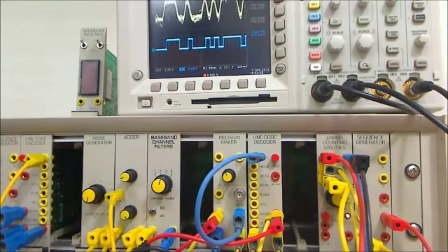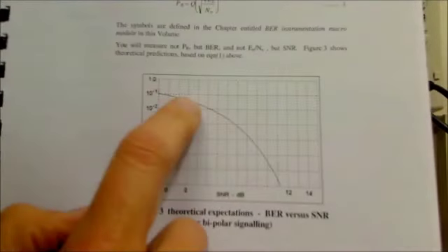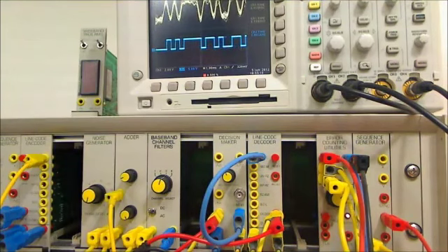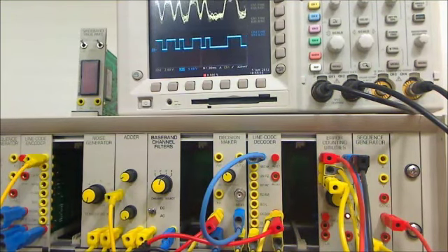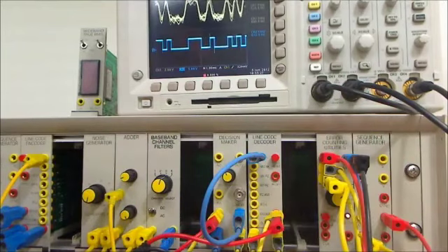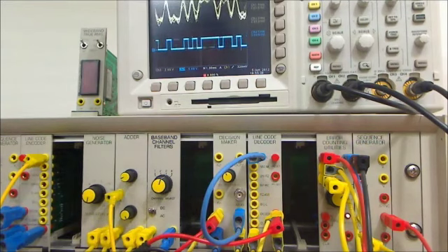So now if you have that bit error rate and the signal to noise level, the student is now able to plot the bit error rate curves versus signal to noise in dB for the system. And using this system, the student is able to compare the performance of this real system with the theoretical expectations. And this same technique can be applied to all the other modulation schemes we have in TIMS, BPSK, QPSK, spread spectrum, and all the other line-coded systems.